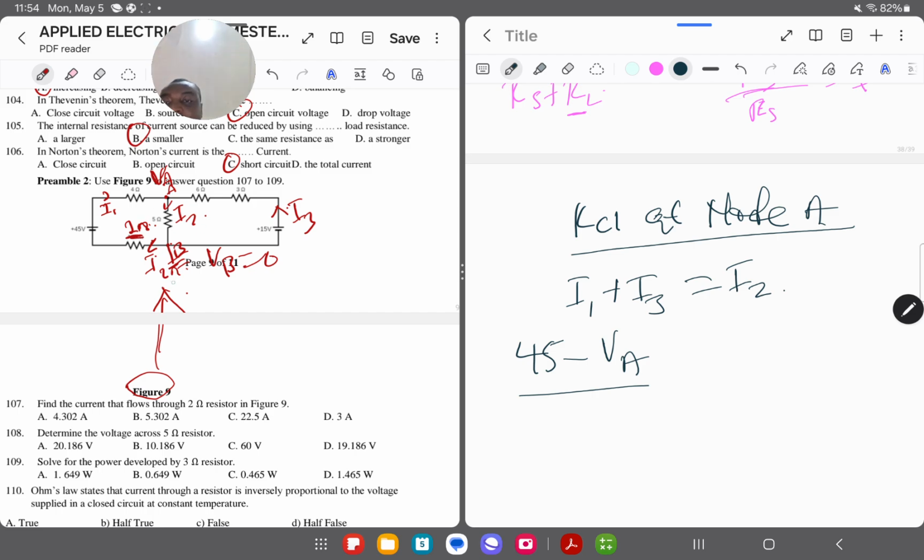So even this I2 that I wrote earlier, it would actually be I1. So the same current I1 flows through 4 ohms and 2 ohms. Because it's the same current, we get the equivalent resistance by doing the sum. So that would be 2 plus 4.